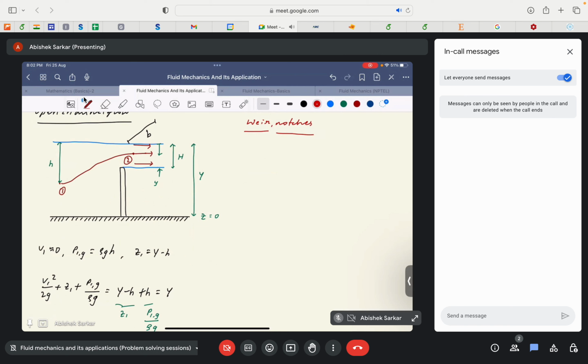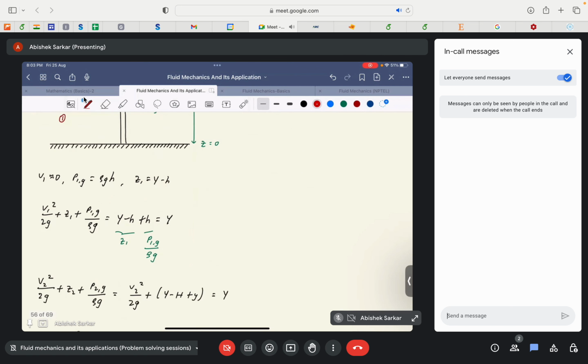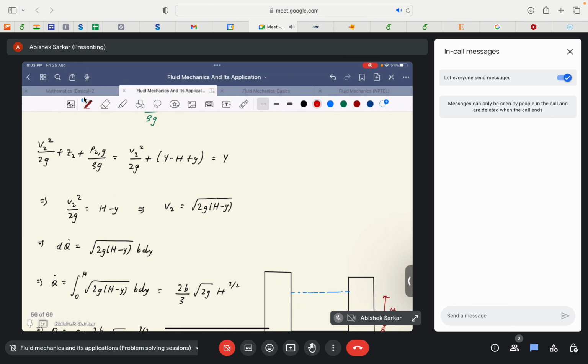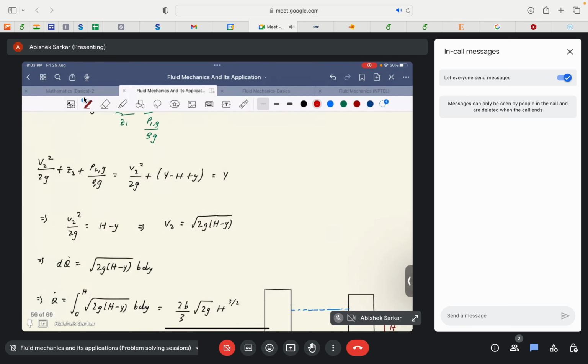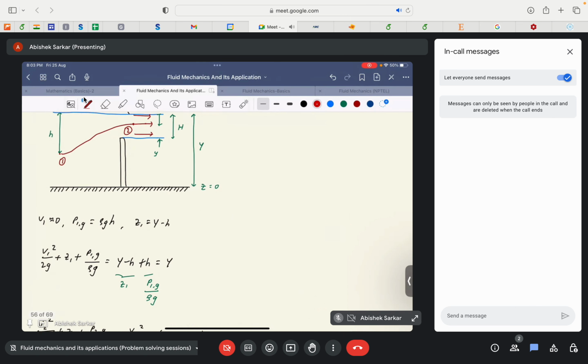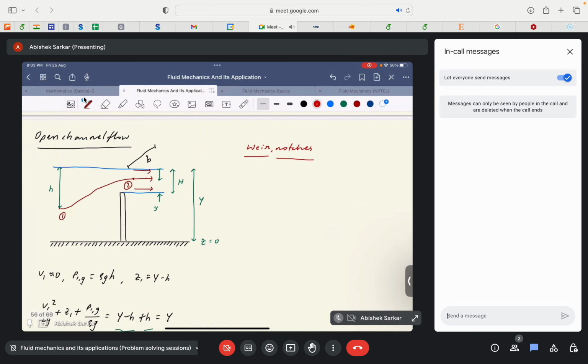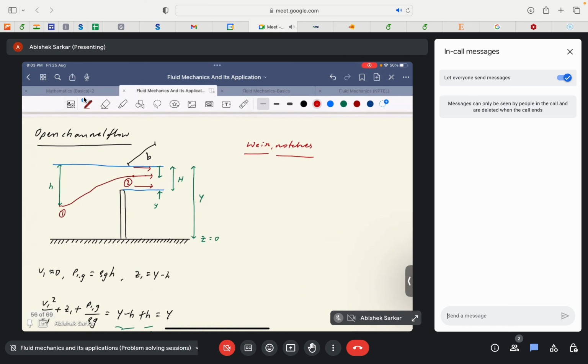The derivation is exactly the same, since the geometrical structures are the same. Assuming a square shaped notch, the flow can be in any shaped channel, but the shape of the notch determines the expression for the velocity or the volume flow rate. That's why I was saying that. Given that the shape of the notch is square, we apply Bernoulli's equation at 2 points in this weir. Consider this diagram, where B is taken to be the width of the notch or weir.